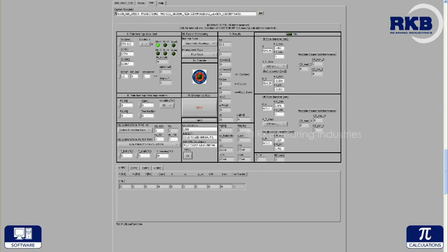In order to determine the inner ring shaft fitting and the outer ring housing fitting, the diameters and deviations of the bearing, housing, and shaft are inserted. The temperature difference between the inner ring and shaft and outer ring with housing are inserted in order to determine the working clearance.